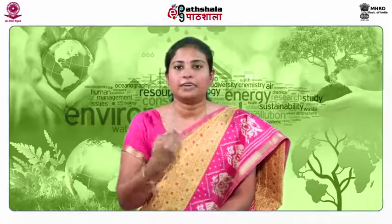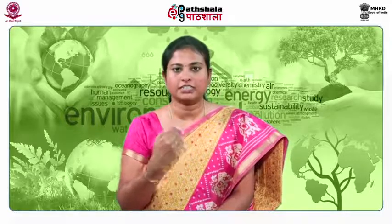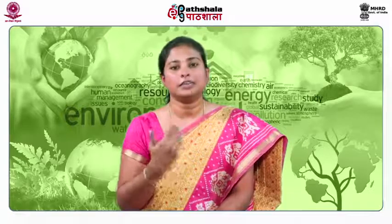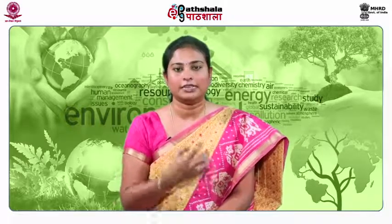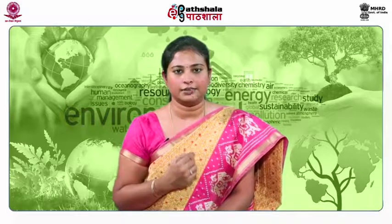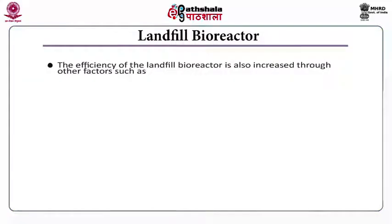At times when leachate is not sufficient to maintain the required moisture content within the landfill bioreactor, you can opt for other liquids like storm water runoff, wastewater treatment sludges, etc. The efficiency of a landfill bioreactor is also increased by other factors. Shredding will improve and accelerate the rate of degradation.